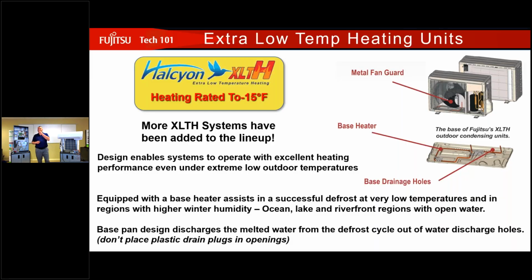Okay, getting to the ultra low temperature heating units. As I said earlier, we have that metal fan guard, a base heater, and base drainage holes. When the base heater is enabled, if there's some sort of frost at the outdoor unit, that's going to melt and become water. We don't want that to gather in the pan, so we have our base heater and base drain holes to allow the water to flow off of that base.